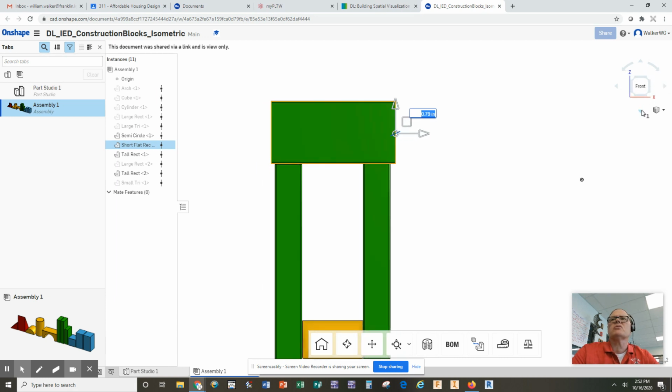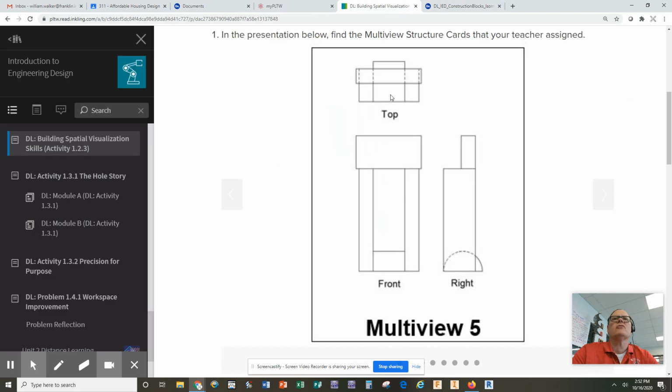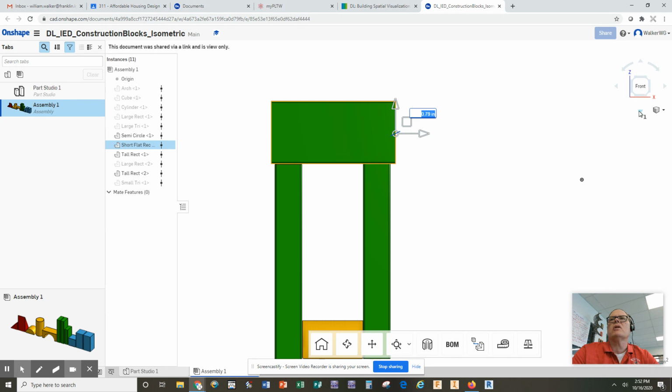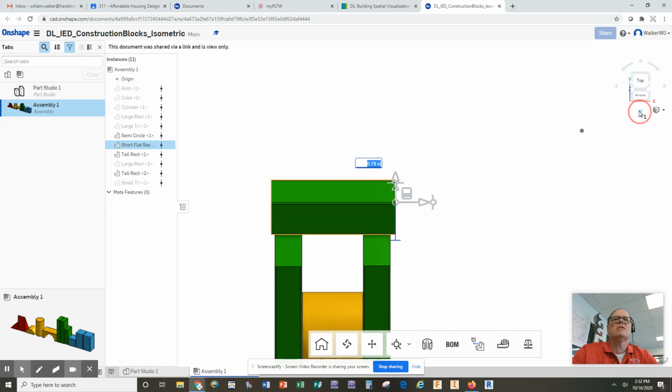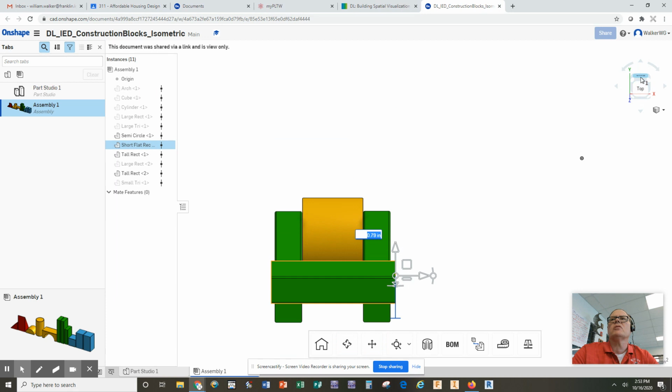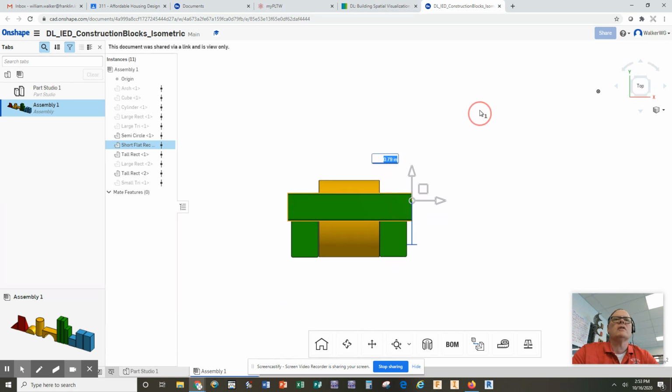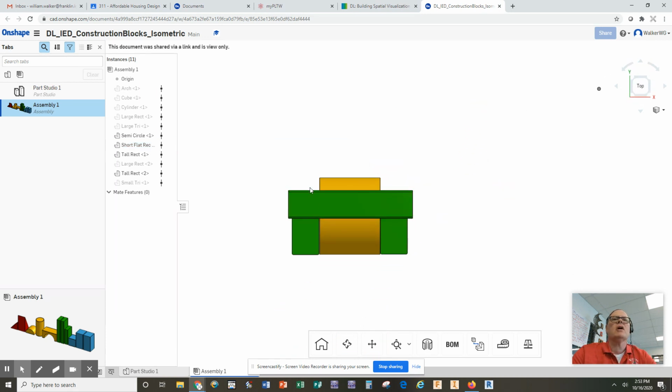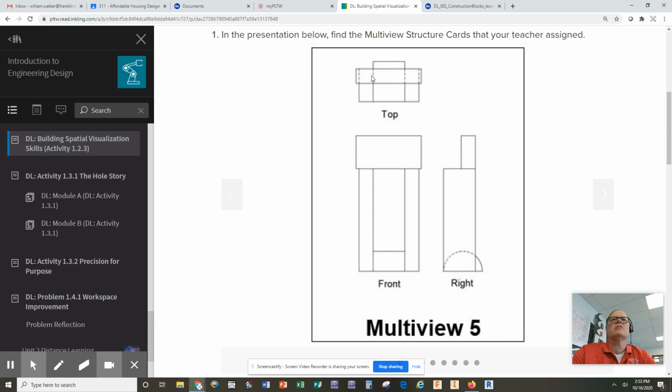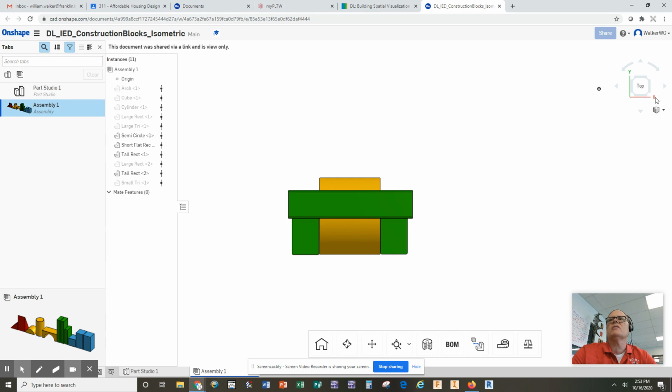And then if you wanted just to make sure that the top view looks like this top view here, with rectangle, rectangle, and a part sticking out of the back, you can actually go and look at your top view here. Okay, so, whoops, went too far. Okay, so like this. Now you notice my top view here, rectangle, square, square, square, rectangle, rectangle, looks exactly like this picture here. The dashed lines mean those are hidden edges. And if you look at your right side view, you can verify your right side view here.